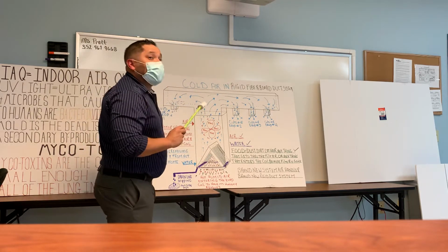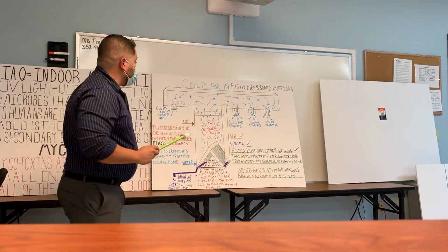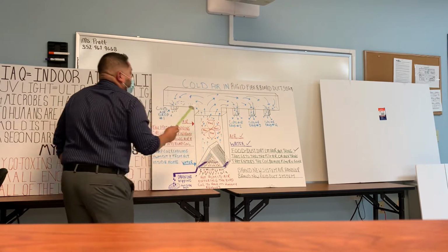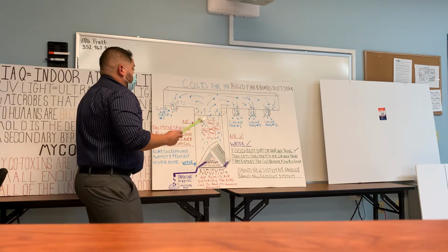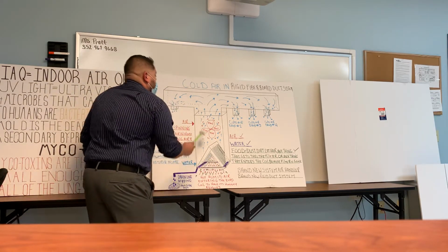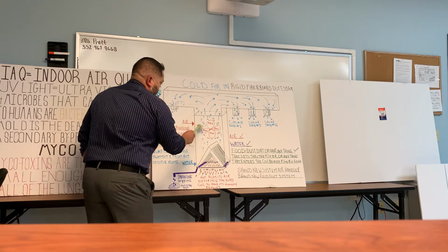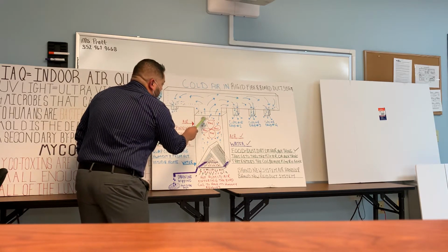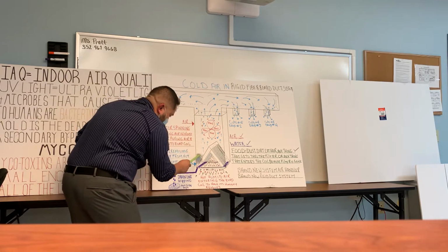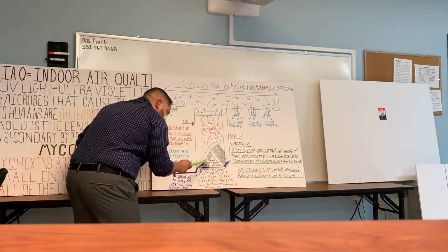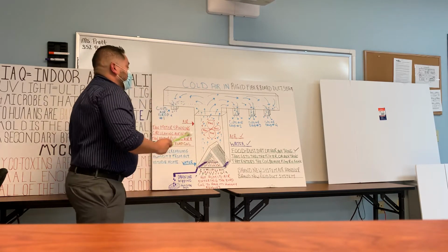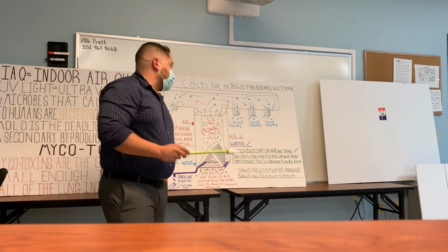Now, the location of the UV light is everything also. In the air handler, all the electrical portions are up here. Many technicians don't know that it needs to be at the bottom of the coil. They will simply install it right here next to the fan motor on a magnet, because it's a lot easier to plug it in here than to run the wire all the way down through the system, drill a hole perhaps, and put the tube in. The UV light has to be at the bottom side of the coil because that is where the air, water, and food initially make contact.